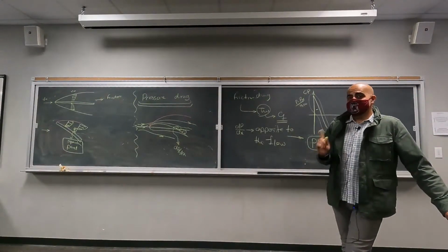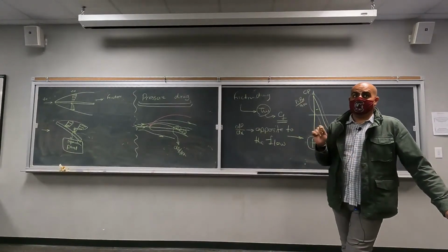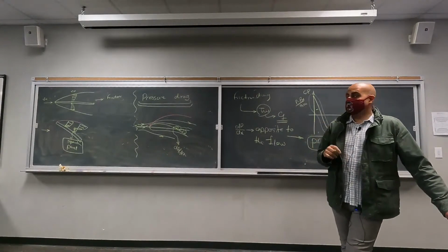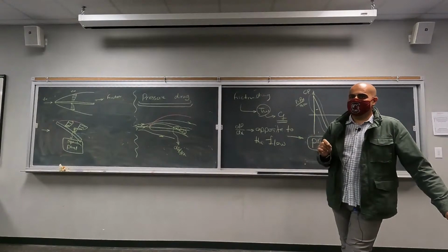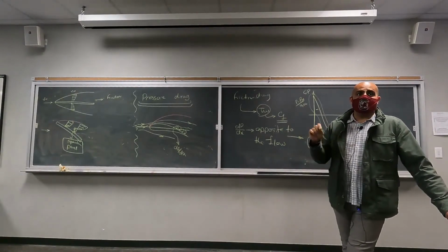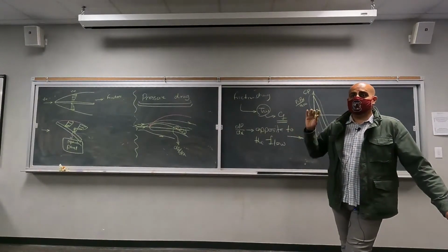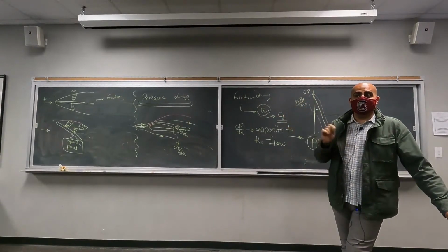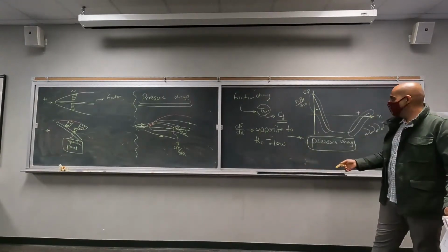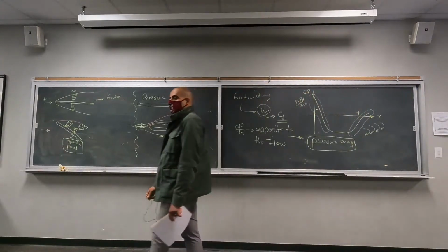Okay, that's good. But one important point remains true, that you need to keep in mind: if we don't consider the effects of viscosity, we won't be able to see this flow separation and higher pressure drag, and we won't be able to see the boundary layers. So viscosity is the main driving factor here, which is going to cause two types of drag, pressure drag and friction drag, okay? Does it make sense?